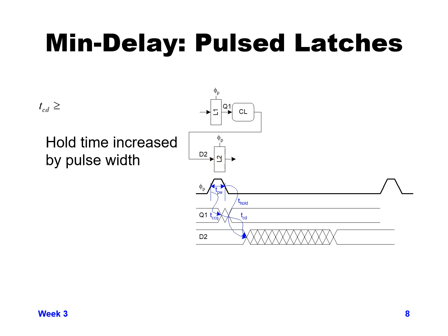Finally, let's go through min delay using our pulse latch design and the analysis. So here we have 2 latches that are both phase 1, but latch 1 and latch 2 have a pulse clock going to them. So in this particular case, when the clock goes high on the first latch, latch 1, as soon as clock goes high, we get a Q1 out. And that Q1 value will have a contamination delay time from clock to Q1.